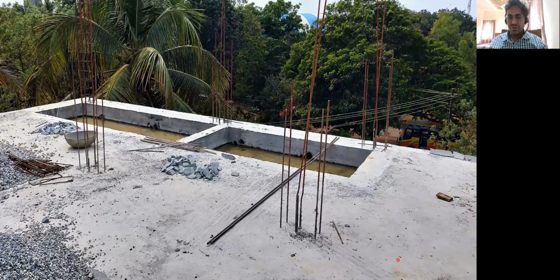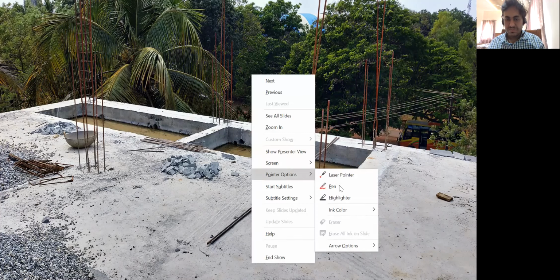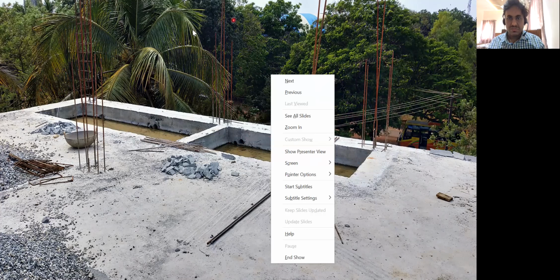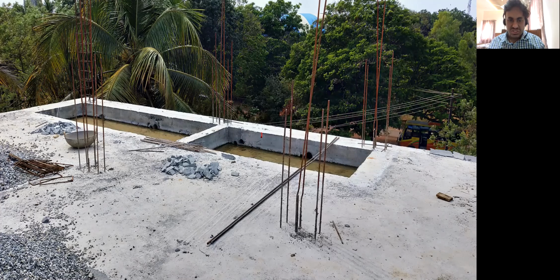If you observe it carefully, you can see all these are the slab, but this was the portion where the toilet was coming, and you can see this slab, right? So you have this slab up to this, but it hasn't been sunk. There's a slab here, but that has been sunk by 300 mm. This distance from the top to here is actually 300 mm. So your toilet floor slab is here, and it has been sunk by 300 mm from here.